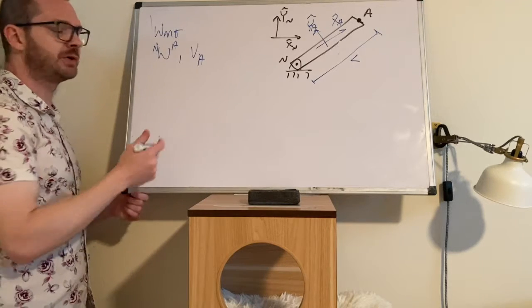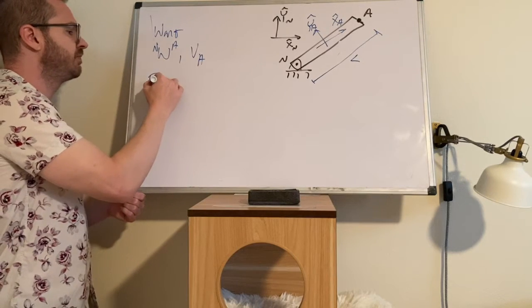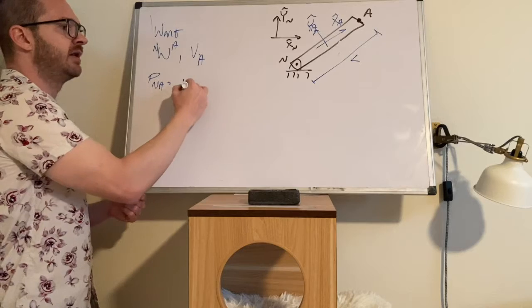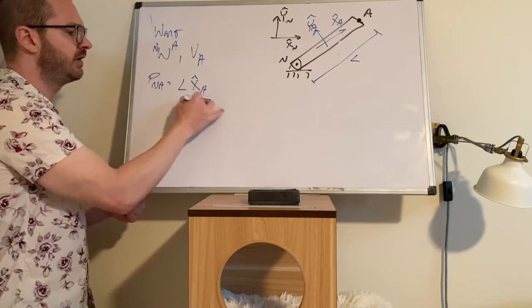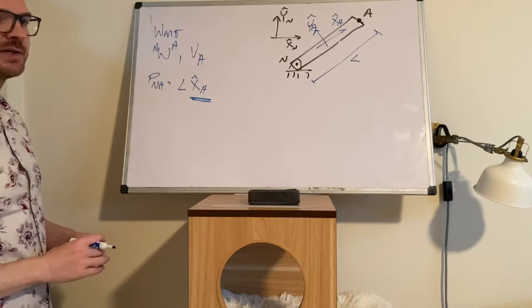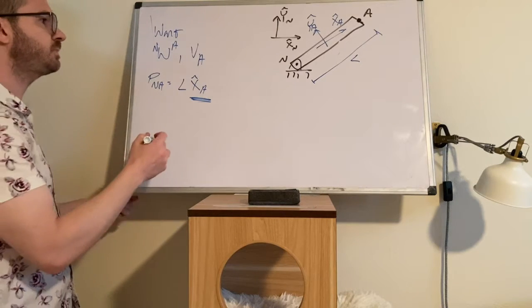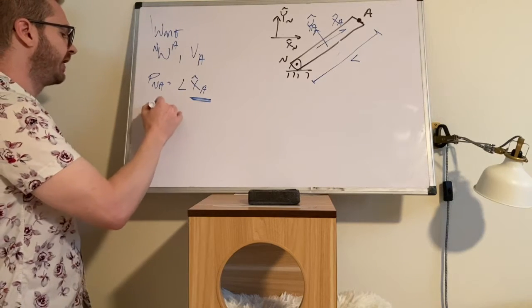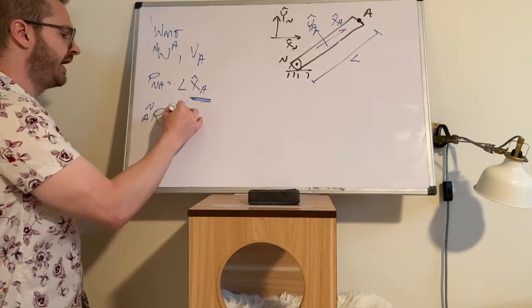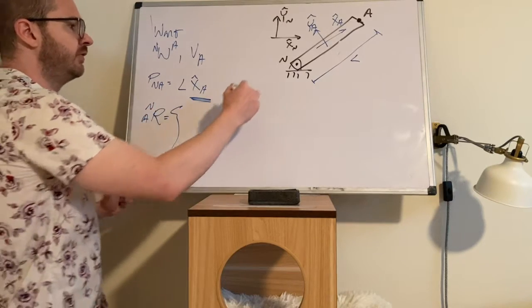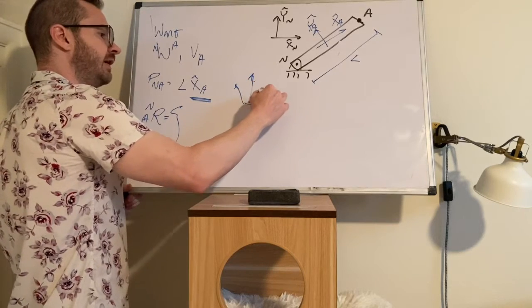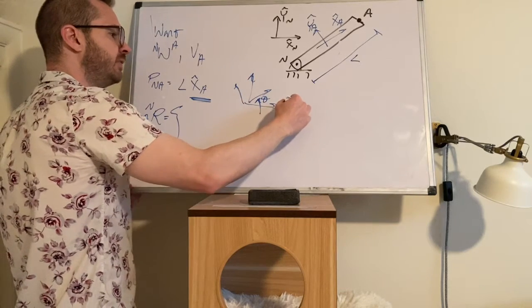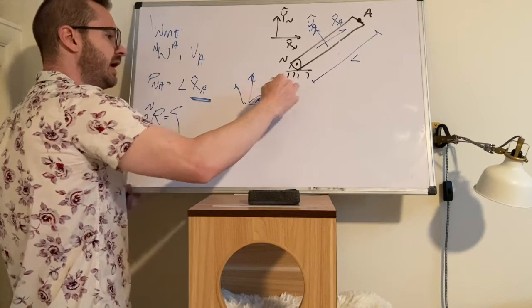By now we know the drill. Position vector, P into A, this is going to be L X hat A. Notice that I'm using the rotating body attached coordinate frame. Next, we need to define the rotation into A. We know how to do that. You do a diagram. There is an angle theta, and this is between the N frame and the A frame.